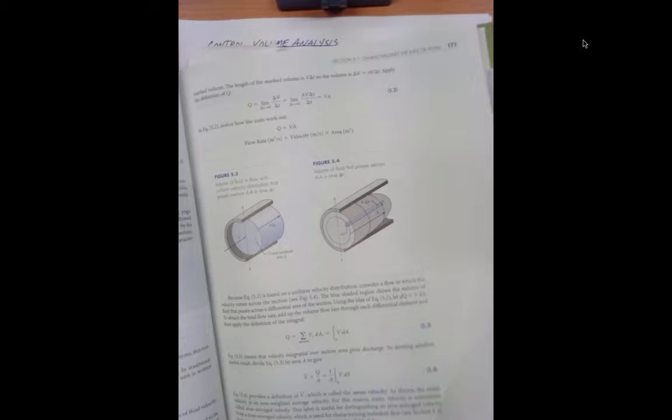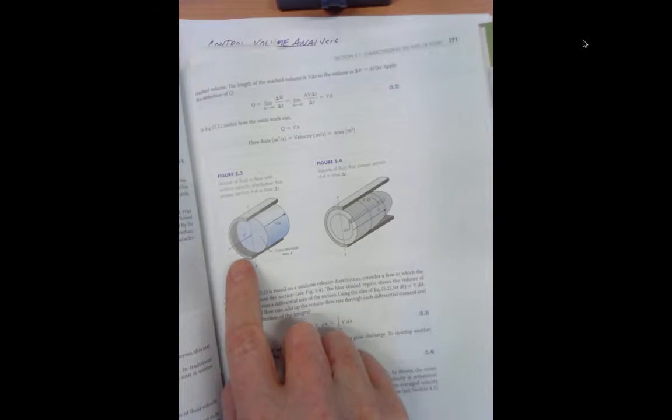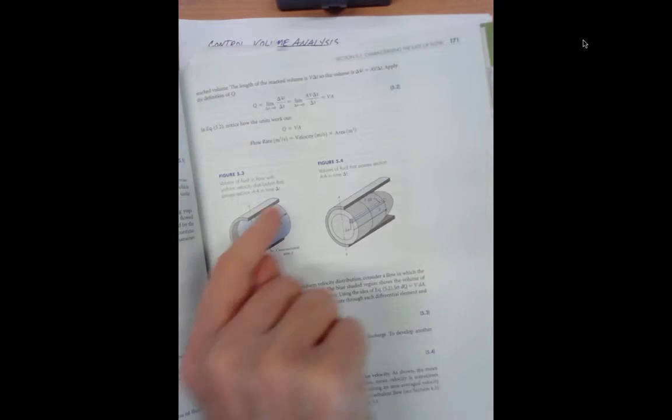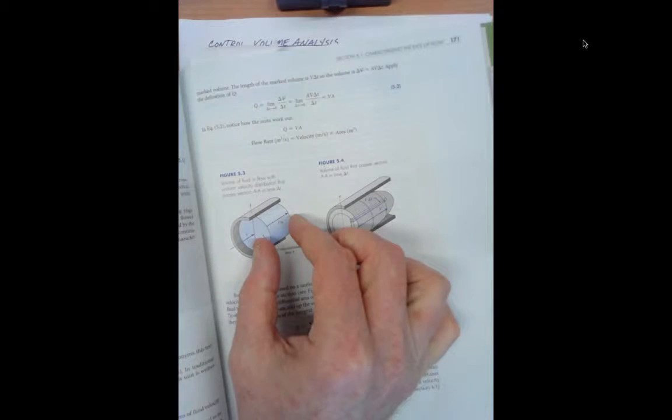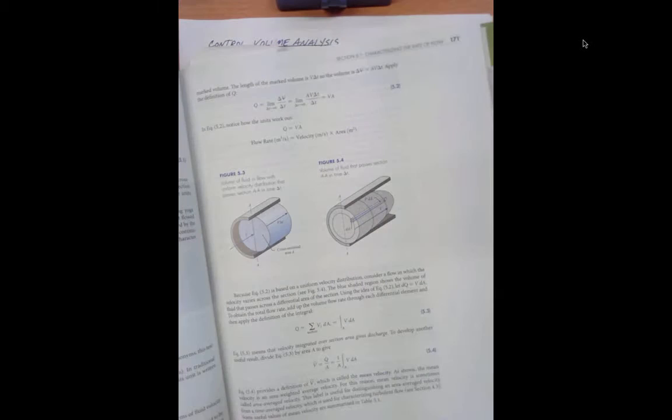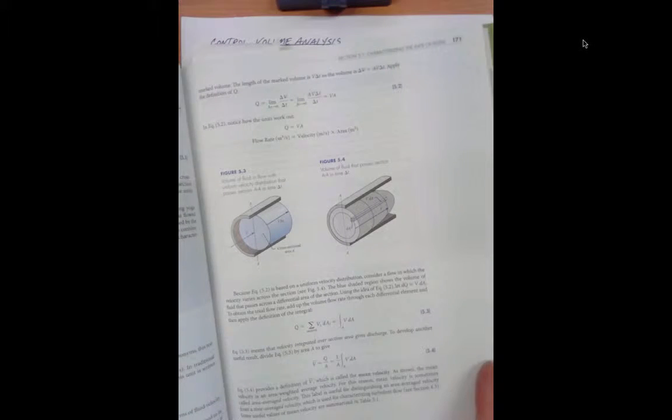It's actually worth taking a little bit of a view of parts of the book to see where we're going. So in the prior 2 or 3 videos we're dealing with these concepts of flow rates, where there's a cross-sectional area of flow, a mean section velocity, and that velocity multiplied by some time interval produced dimensions of a volume, and so the amount of volume per unit time is what we call the flow rate. Usual symbol is Q.